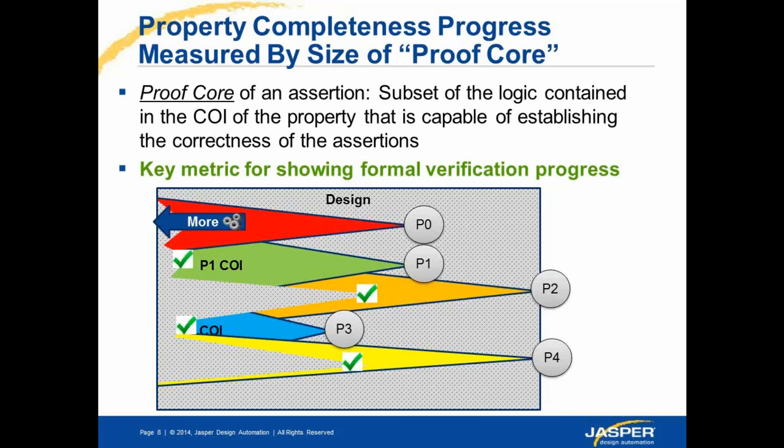And the engine uses a lot of optimizations like constant propagation, honoring constraints, cut points, and a lot of other non-deterministic optimizations to actually slice a portion of the fan-in cone here, a portion of the fan-in cone there, and you end up with a picture like this. Eventually, when the problem is presented to the engine, this is the picture the engine sees. Now the cones are not whole anymore, as you can see.